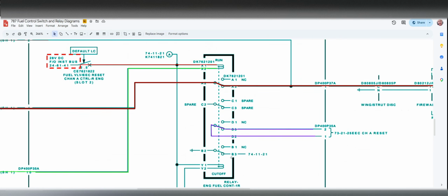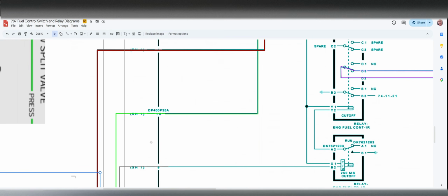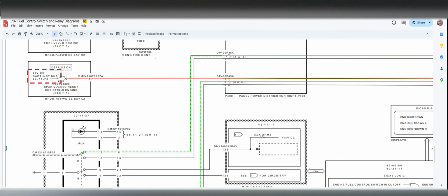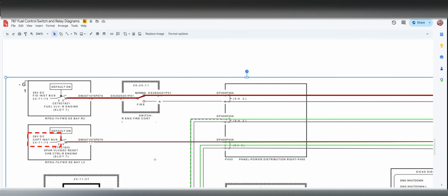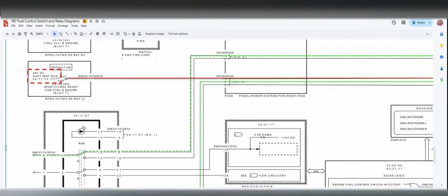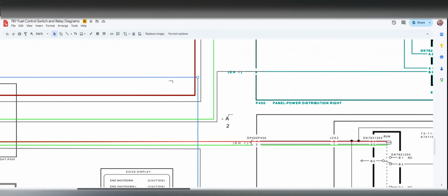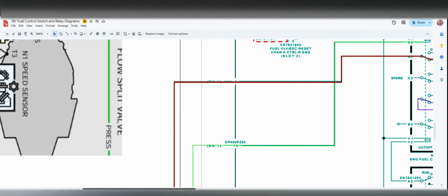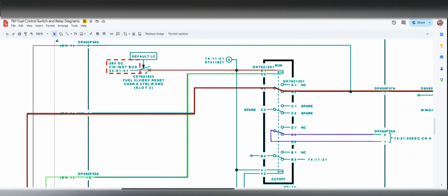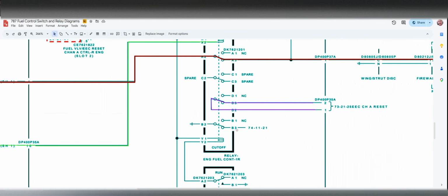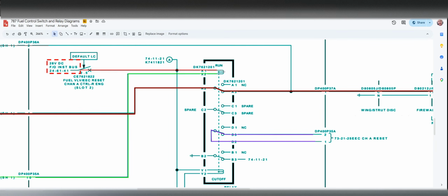The same can be said for the high pressure shutoff valve control circuit. Let's have a look at that. As for the other one, going up, run, follow the run wire, up, into the high pressure shutoff relay. This is relay 1, there are 2 per engine. Reverse that through the run coil, set the run coil to push instead of pull, backwards through the reverse current DC buses through the broken diode, and you have a commanded shutdown.